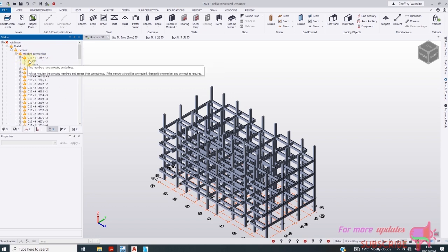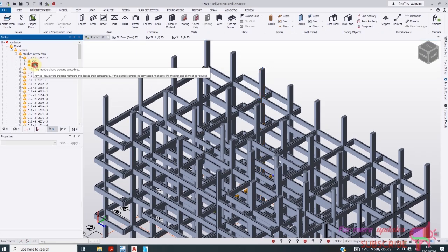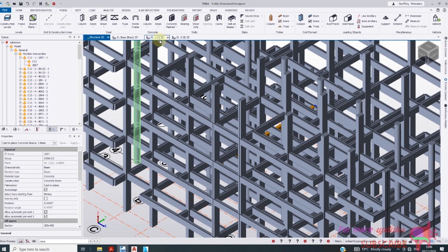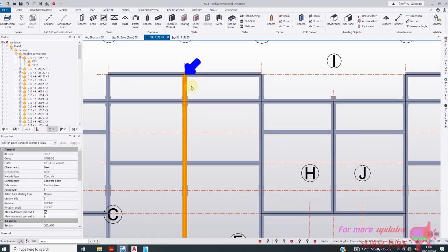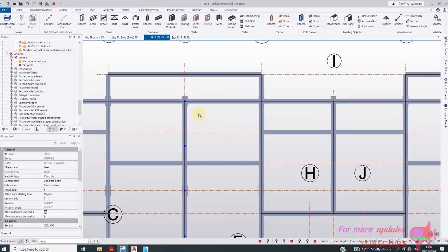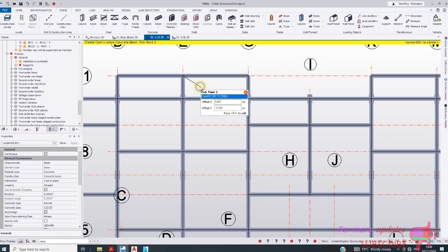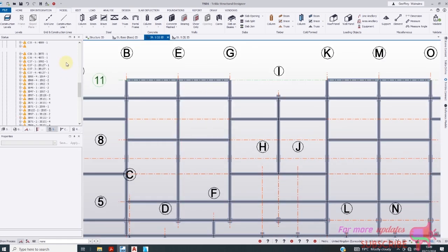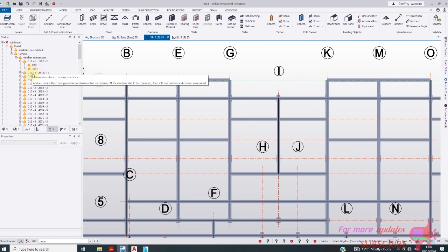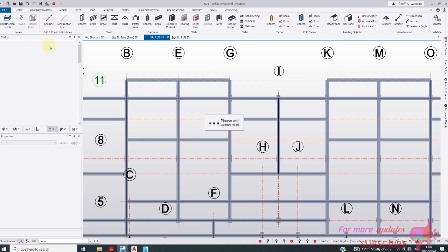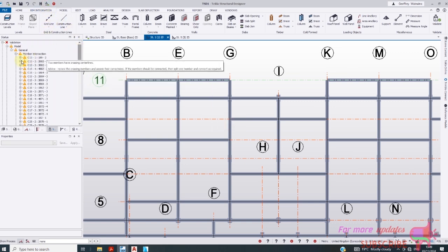Now we are in C12. It's saying that column and that beam. So if I go to first floor, I just need to pick this and then this, drag it to that point. Then instead, I will draw a beam up to that point, double click. So this one, I will escape. This one will change in all the levels. So this one was C12. Let's now validate again. C12 should disappear. We do the same to C13.